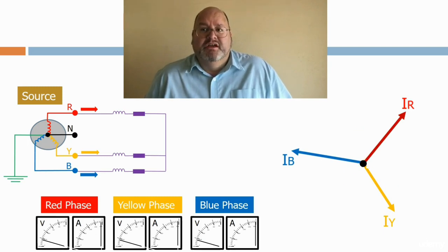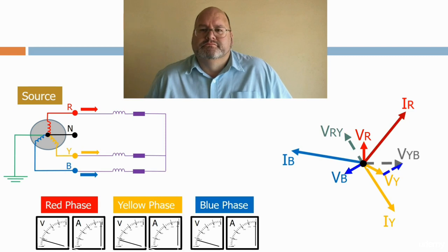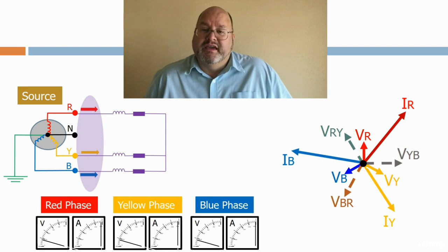All three-phase voltages will now reduce substantially, but they will remain in phase as the voltage is balanced. Let's now look at the line voltages. All three line voltages will now reduce, as the phase to neutral voltages have reduced in magnitude, although they will remain at the same angle. If we now try and summate all the currents, it will still equal zero, as although the currents have increased substantially, there is no current leaking out of the system.